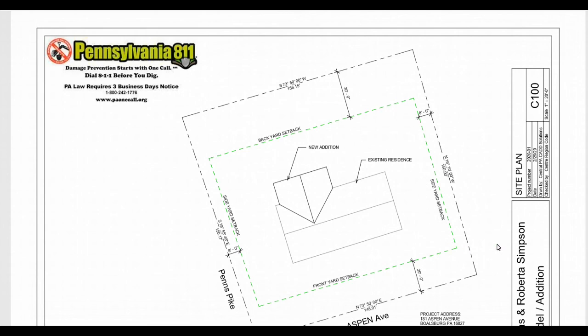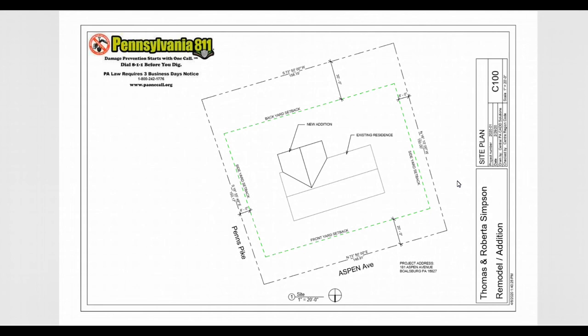A lot of times what will happen is these site plans can also include a grading plan, which has the topographic information on it. It can show where any ditches or swales are, basically how this piece of property is going to drain. And I've worked on a lot of commercial projects in the past where the first rule is all of the water that lands on your piece of property needs to be contained within your site. You can't just make a great big ditch and have it go over to your neighbor's property, so you have to contain it on the site.